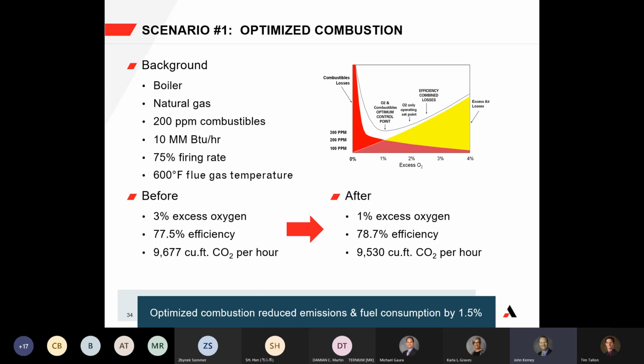Okay. Thanks, Tim. Just to follow up on that, what's the advantage of adding the methane measurement in addition to the oxygen and the combustibles? Well, that would provide further safety monitoring for fuel leaks and for flameouts, because in those scenarios, you wouldn't necessarily be able to monitor for unburned methane, if you will.